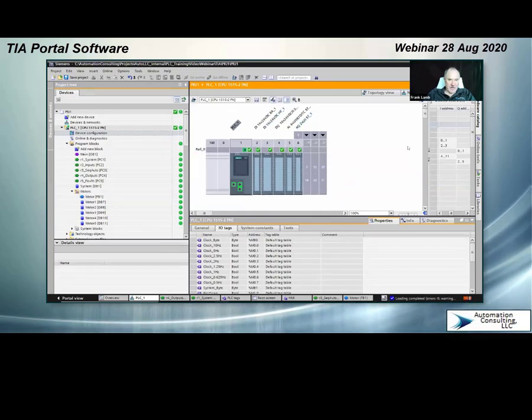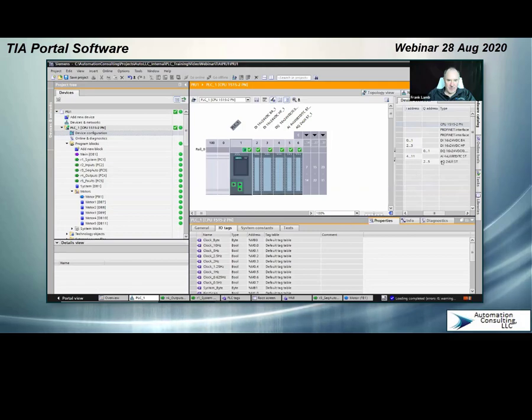Okay, so this was my hardware layout. I did a couple of input cards. Then I did 1 output card. Maybe I did 2 output cards. Or is that another input card? It looks like maybe it's another input card. No, it's an analog input card. And it used word 4 through word 11. So that would be 4, 6, 8, and 10, right?